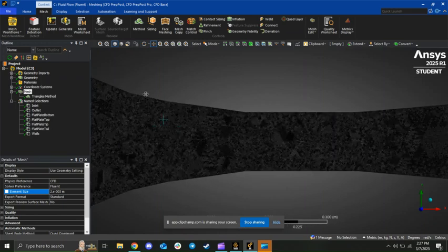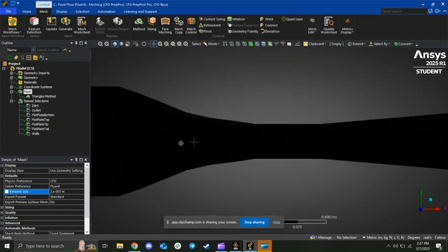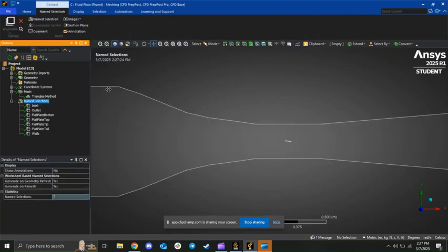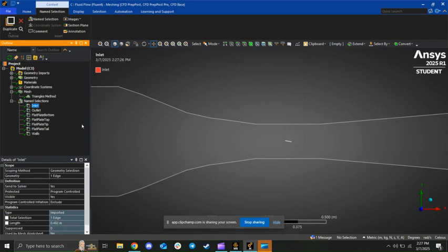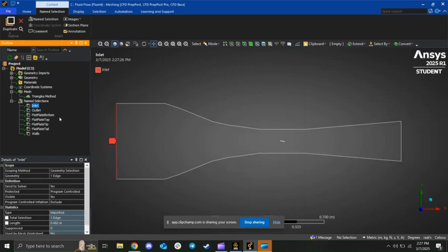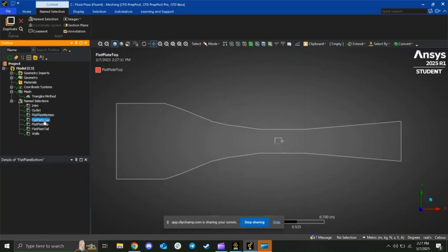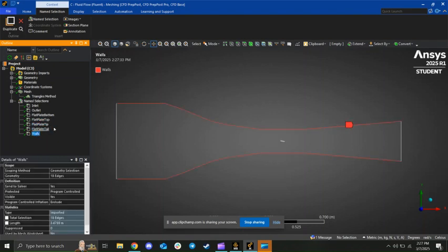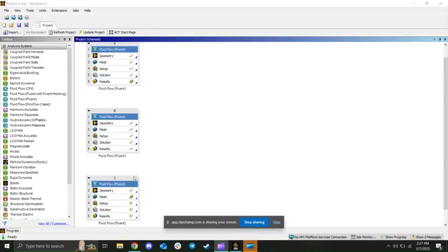So like I said, just like in the previous lab, you just click method and then select the method that was needed. In this case, it was triangles, the area that needs to be generated. And then if you needed to, you'll just go to name selections and then just start clicking on the pieces and then name them. So that part is easy. It's just like the previous parts. So moving on, closing our generator.